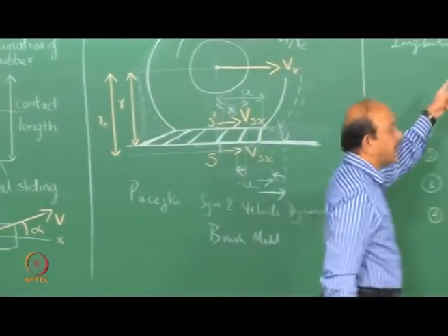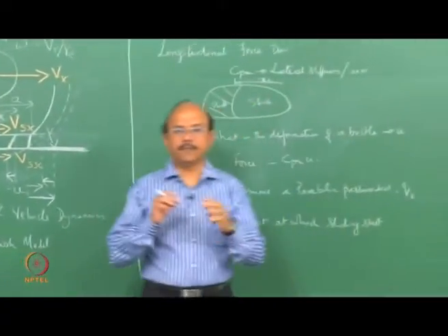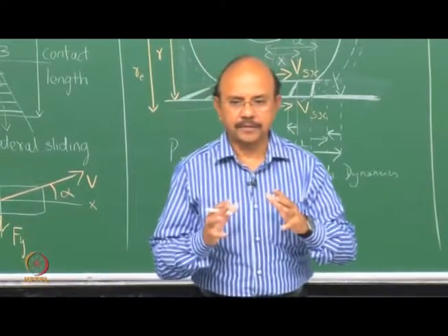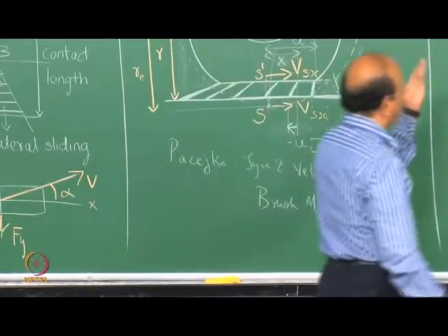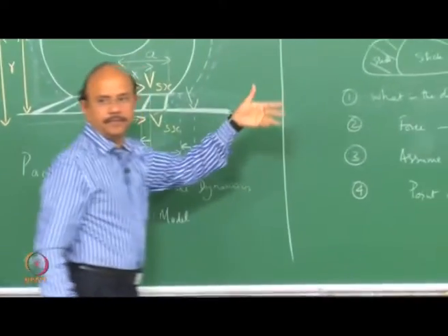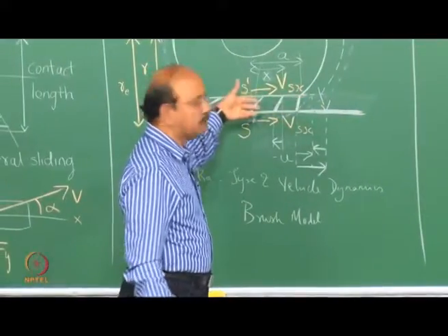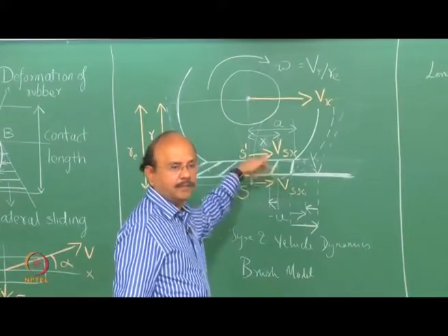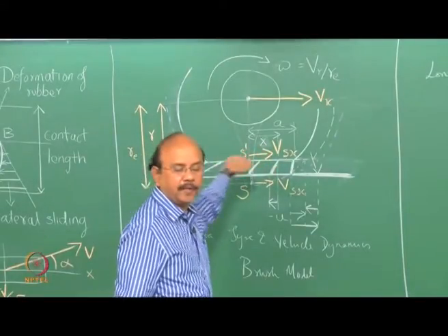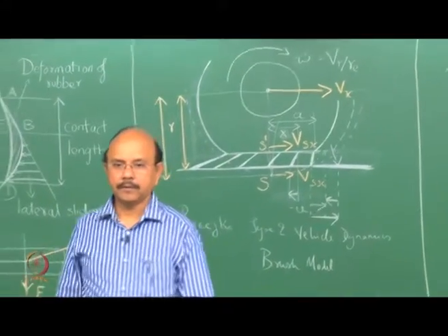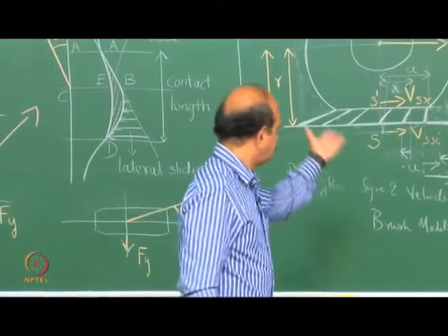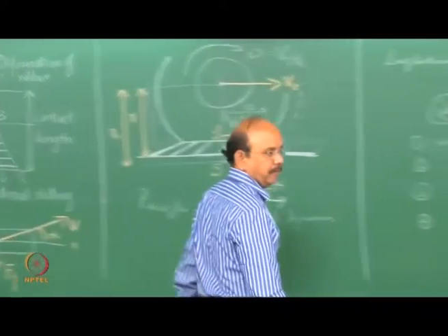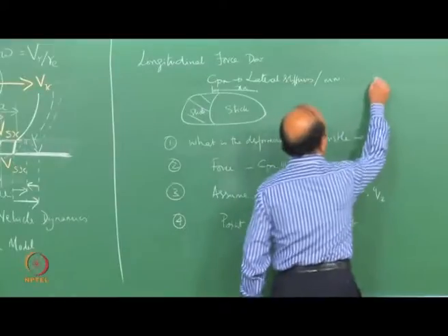Yes, this is a Cpx, the longitudinal stiffness. A good question. Please understand that these bristles have two stiffnesses. Now you know what is stiffness. The stiffness is here in this direction. And stiffness can also be in a direction which is perpendicular to the plane of the board, which you would call the lateral stiffness, which is Cpy. Okay, so Cpy is the lateral stiffness.